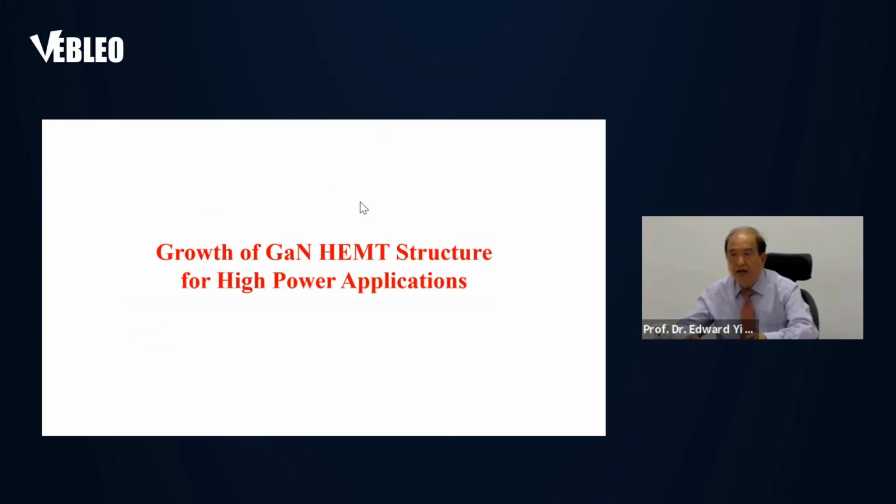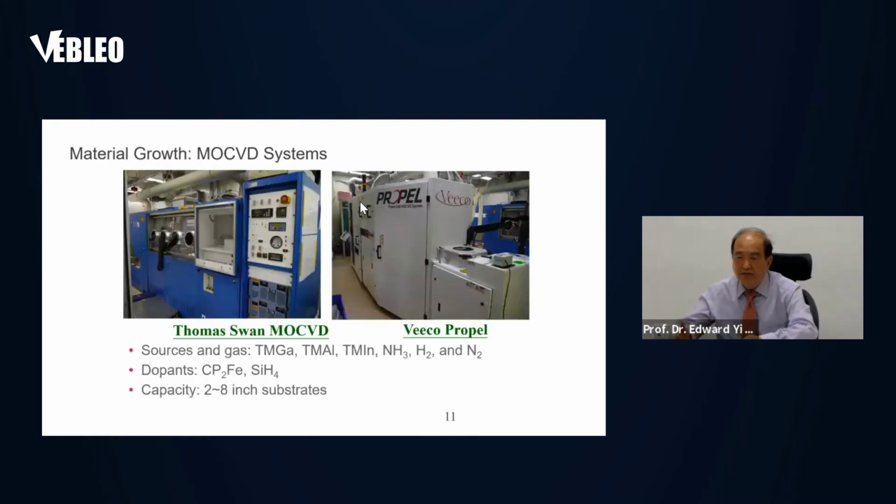Okay, and then this device technology starts with material growth. Gallium nitride is grown on silicon to reduce the cost. The reason it is difficult is because gallium nitride and silicon have a lot of mismatch in the crystals, because the lattice constants are very different for aluminum gallium nitride, indium gallium nitride, and silicon. Because there is a lot of mismatch, you need to tune the stress. Usually we grow by MOCVD, and in this work we mostly use vertical-type reactors, growing on silicon, and these are the cases used in this growth of material.